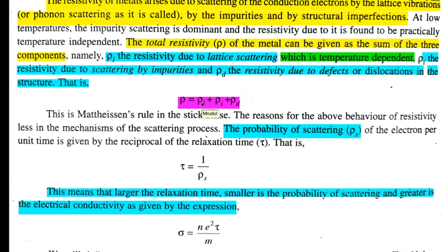So during this phase, what are the possibilities to scatter the mean free path or the mean free time, or disturb that, and that is what contributes to the resistivity. So the very first point is that resistivity could be because of the lattice scattering, meaning the atomic position or host ion causes the scattering, the scattering because of your host ion, and which is strongly temperature dependent.